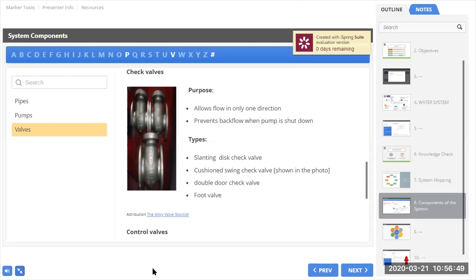Two important ones: the check valve is one, but the air gap is the one that prevents any form of cross connection from happening, because there's a certain distance in terms of air distance between the part that allows water to come in from the distribution system and the system that the water is going to. Okay.